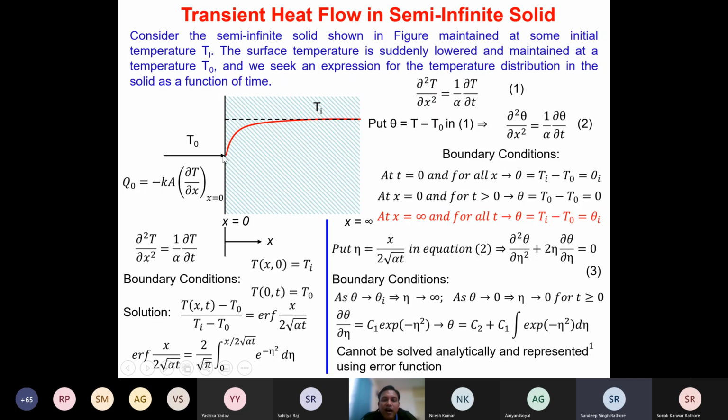infinite in terms of this heat transfer, isn't it? Because my conduction is becoming 0 at this point, so still that length can be infinite. So what length I should take as infinite is difficult to obtain in such cases, correct? This is what happens even in the Couette flow. So in such cases, solving the differential equation is possible only if you non-dimensionalize this differential equation. Otherwise you will not be able to solve it.